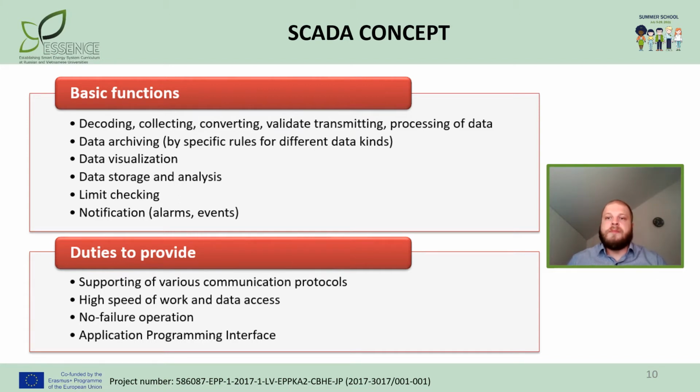Some of those sensors measure simple events that can be detected by a straightforward on-off switch called a discrete input or digital input. In real life, discrete inputs are used to measure simple states like whether equipment is on or off, or tripwire alarms like a power failure at a critical facility. From the point of view of the power system, a discrete input could refer to the state of the circuit breaker, switched on or switched off, which is very useful to monitor the topology, the configuration of the power system in general.